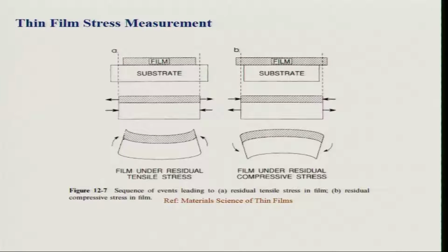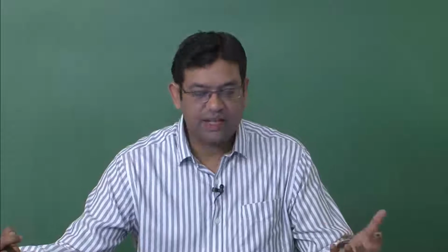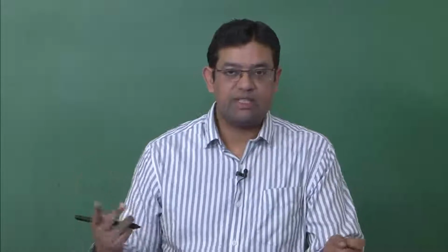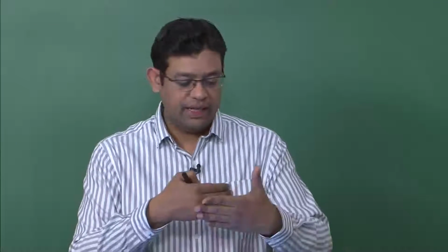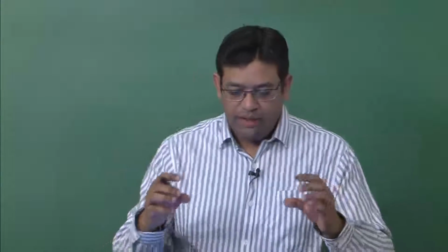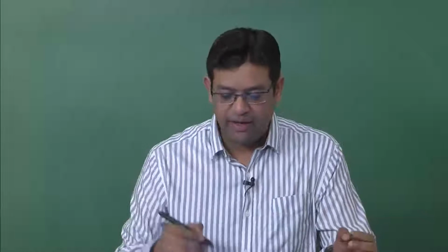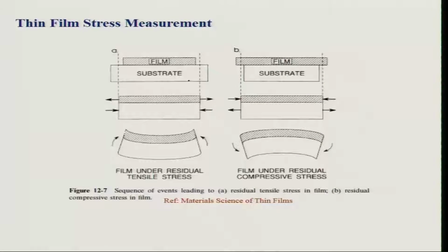Now, we will come to stress. We were discussing that very often these thin films have stress, and these stresses are due to two reasons. First, they are different materials, so they would have different lattice constants and different adhesion. When you try to match substrate and film which have different constants, often the film will be under stress.